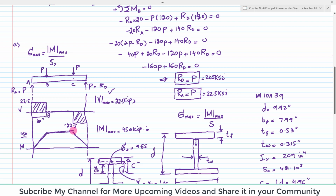So this is plus 450 and minus 450 will be equal to 0. So this straight line will be the bending moment diagram for this portion C and D. Since this shear force is negative, the bending moment will be minus 450 and this will be downward. So from this we conclude that we have a maximum shear force of 22.5 kips, and from bending moment we have maximum bending moment 450 kips into inch.